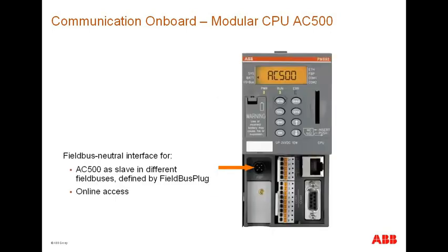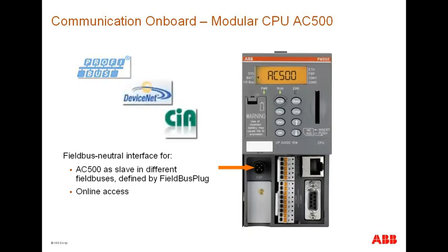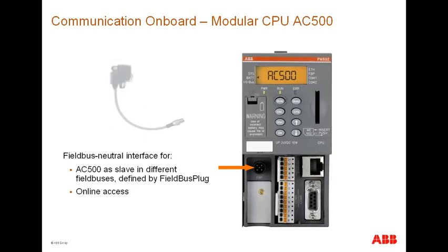Coming to the fieldbus plug, which is also an integral communication port in the modular CPUs. This powerful interface allows the modular CPUs to be configured as a fieldbus slave, supporting most of the renowned fieldbus communication protocols, like Profibus, DeviceNet, CANopen, etc. The type of fieldbus supported is determined by the fieldbus plug that we use, which means there are different plugs available to support different protocols.